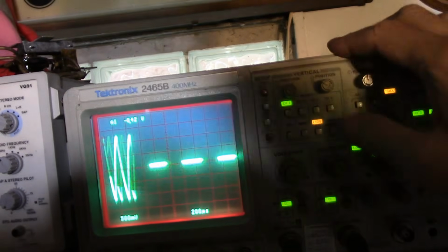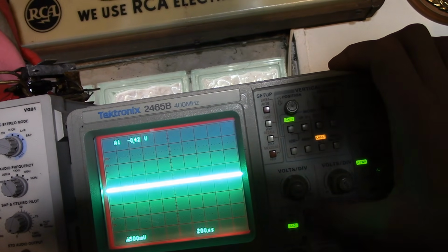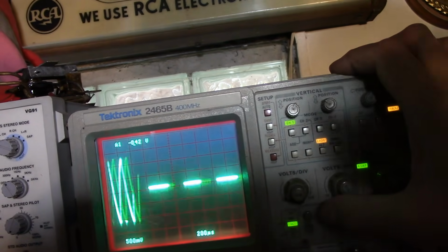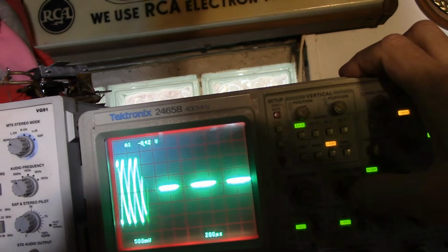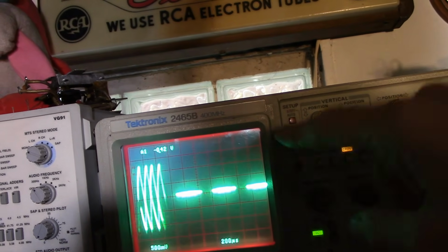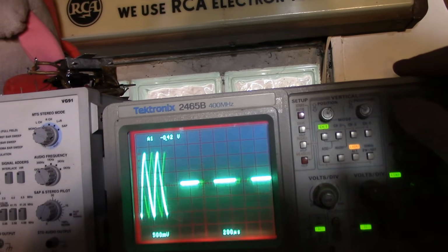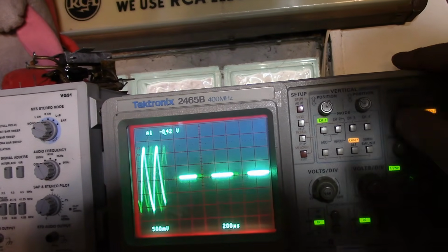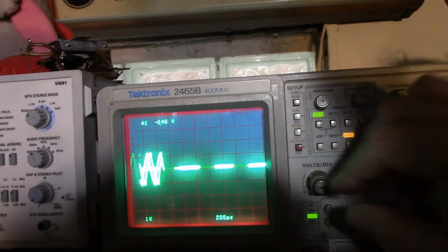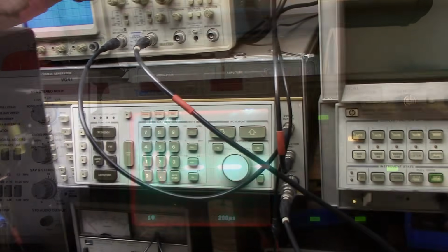So, let's see, is this... Okay, that's ground in the center there. So it's going plus minus 1 volt. The back of this is TTL, so I think it wants more like 0 to 3.5, 4 volts, 5 volts, something like that. And this is only doing about 1 volt. Yeah, just a little more than 1 volt. So I think it doesn't have enough amplitude to do the intensity modulation.